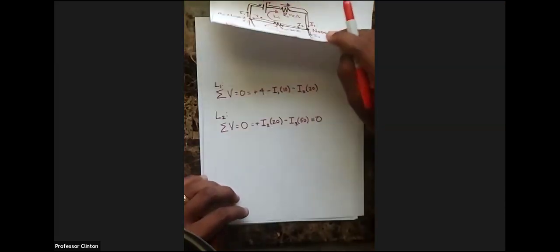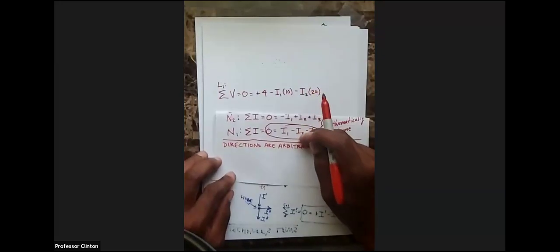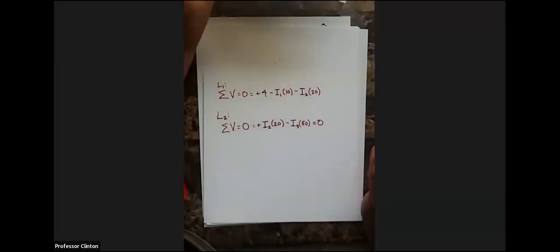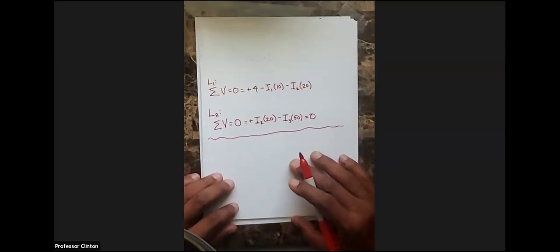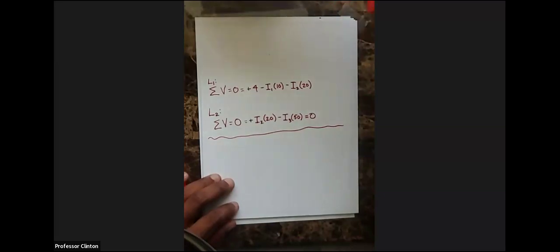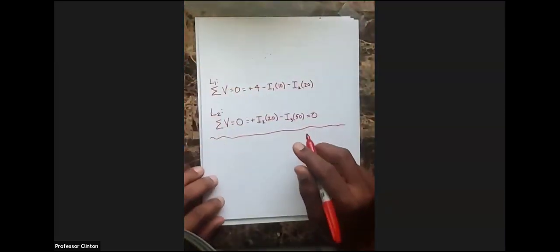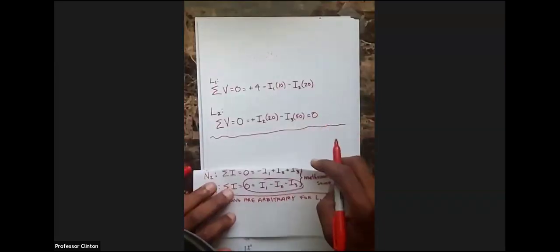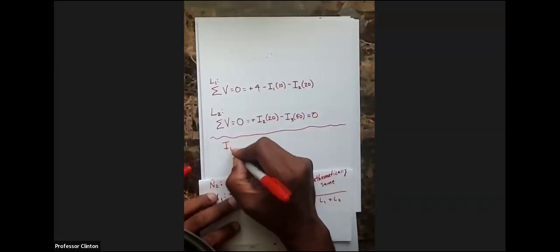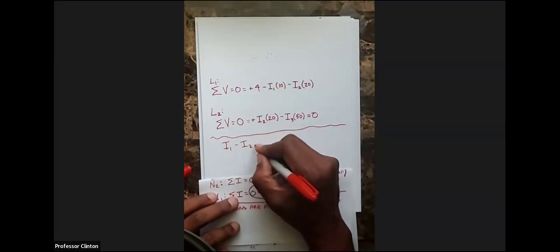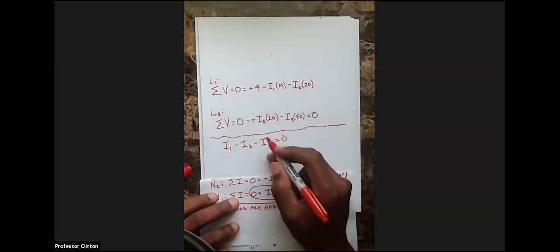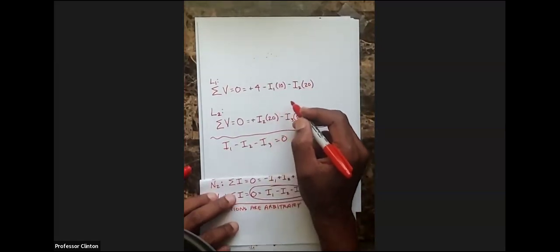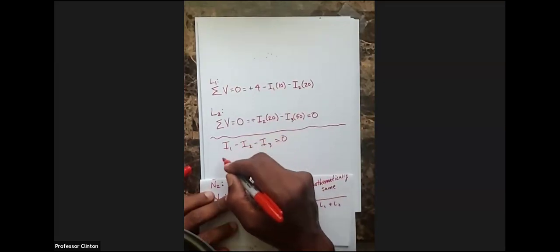And they come as a byproduct also of this. If we have 3 unknowns, we need 3 unique equations. Going a little faster here, the first equation from the node piece, the junction rule, we have that I1 minus I2 minus I3 is equal to 0. We picked one. From the voltage rule, we'll put these in a cleaner descending order, if you will.